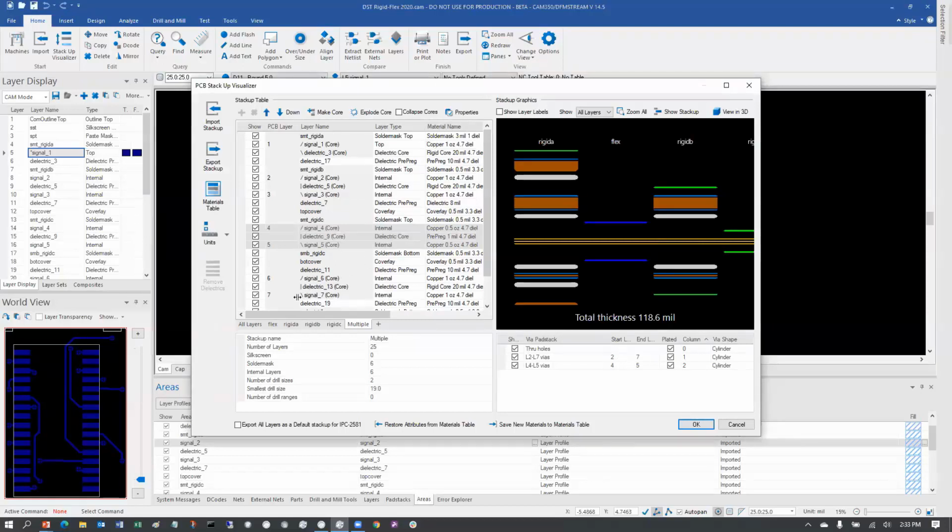Now, sometimes you're working with a large design and it might have a lot of cores in it. And cores, as you can see, when they're identified, there's a graphic appended to the layer name and prefixed to the layer name, so that you've got core and the backslash. Those are just graphic pieces added in the dialogues. They don't actually change the layer name. It just gives you a visual that, hey, these are a core.